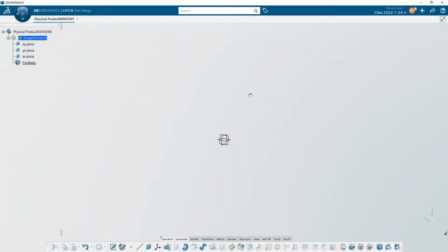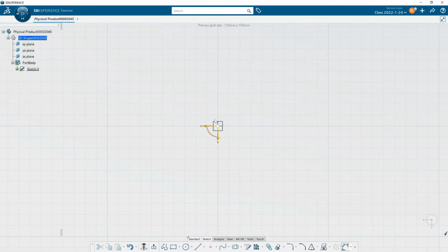Okay, so I'm going to do this again because I talked a lot as I was doing it. Now I want to do it fairly simple. I want to make a disk, and I want it to be a certain size. So I'm going to click on the background to deselect everything. I'm going to go to Sketch, and I'm going to pick a plane, which is a little bit backwards from the way I did it before. I'll hit this plane, and then right here, I didn't talk about this before, we have our sketch axes. I can change these things around if I want and click on the background. It solidifies. Don't worry about that right now.